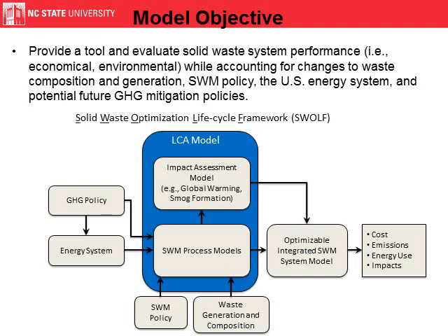But when we take those coefficients and put them into an optimizable integrated solid waste management system like SWOLF, we can now look at all of the potential waste process choices and waste flows and try to find the best system that meets our objectives subject to our constraints over the time horizon we're interested in. And then it can tell us the best choice of technologies, how to phase them in, where different waste components should be treated and how they should be treated, as well as the cost, emissions, energy use, and environmental impacts associated with that system.